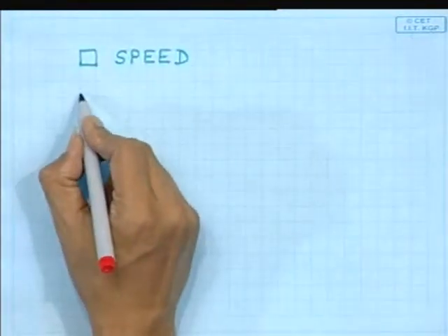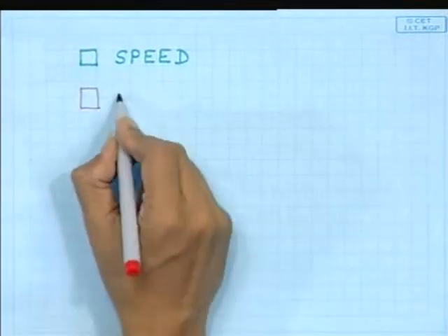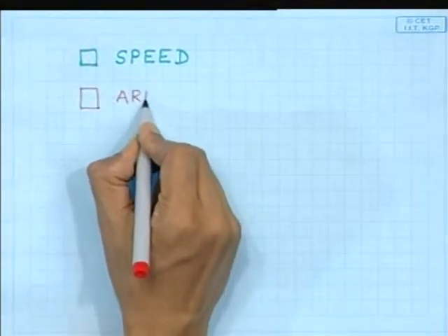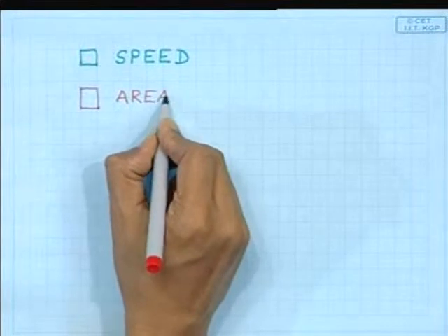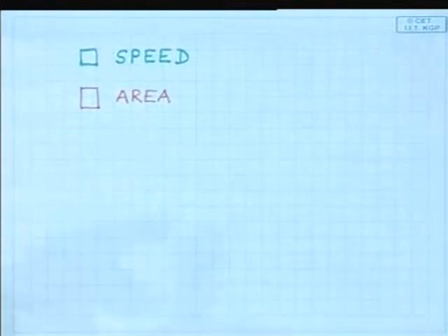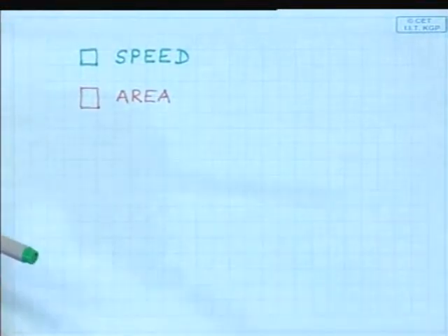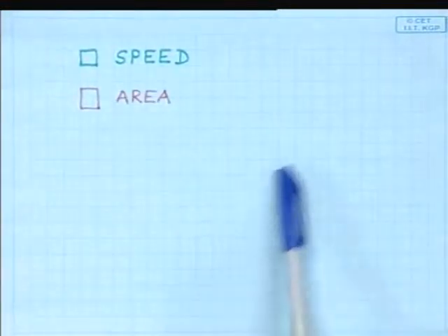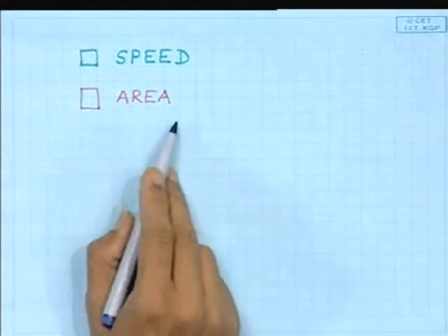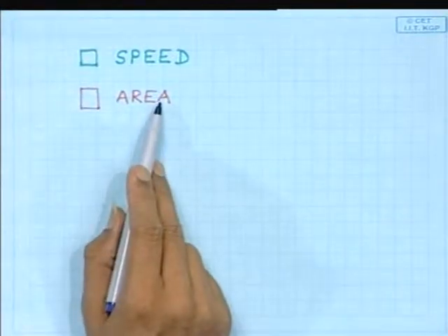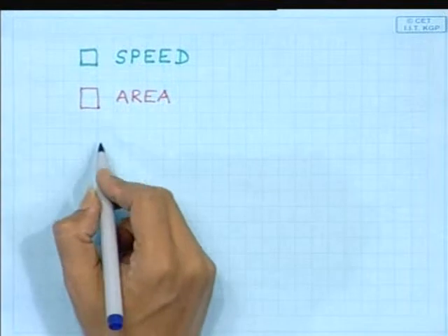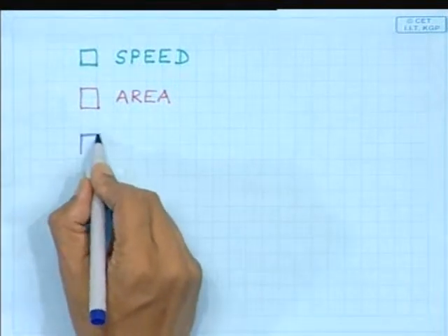So other than speed, you are also having another concern, that is area, because particularly for some commercial houses producing those ICs, the area is very important because area decides the cost of the chip. On one single wafer, how many chips they can make. If they can increase the number, then obviously their production cost will be less per chip.